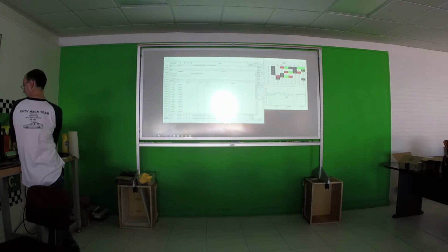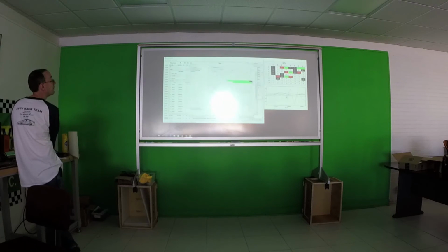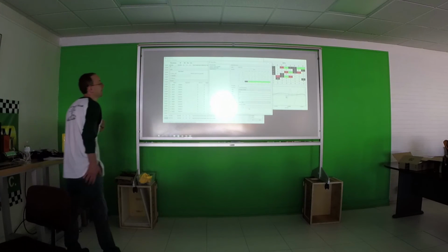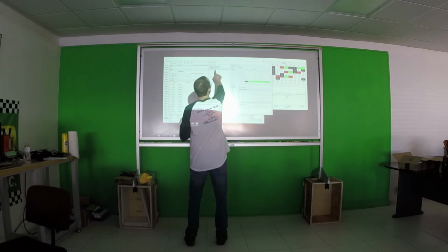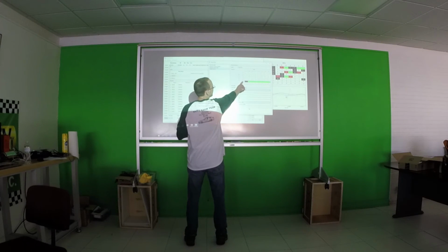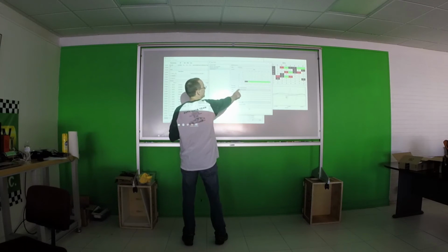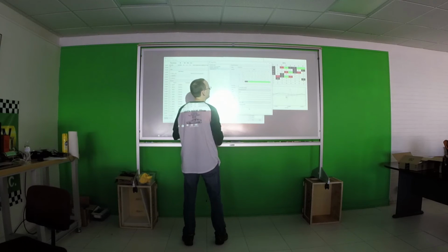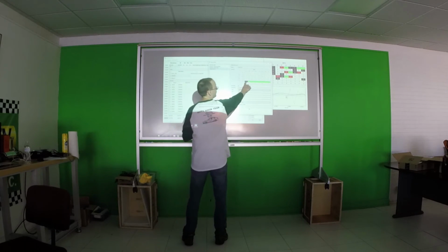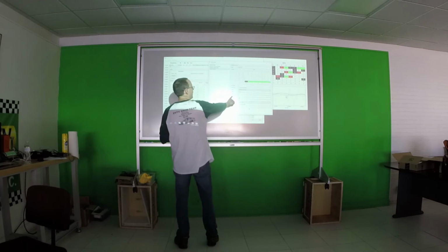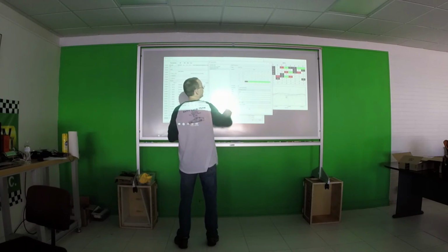I'm clicking here to the signal editor and come up with the messages that the inverter sends in ID 106. Its motor RPM, torque filtered, torque raw, and throttle are found in here. Now this is where the DBC editor is nice. You can see that the throttle is stored in byte 6 here. It's stored across the whole thing. The byte length is 8. It doesn't matter whether I select little endian or big endian, because it's all in the same byte. But they also scaled the throttle by 3.92.